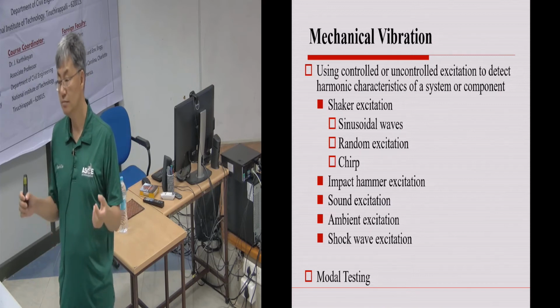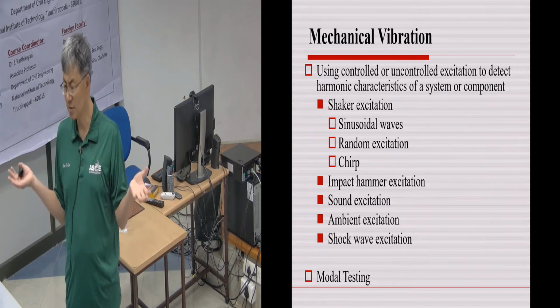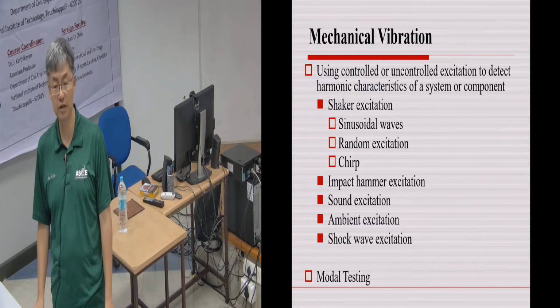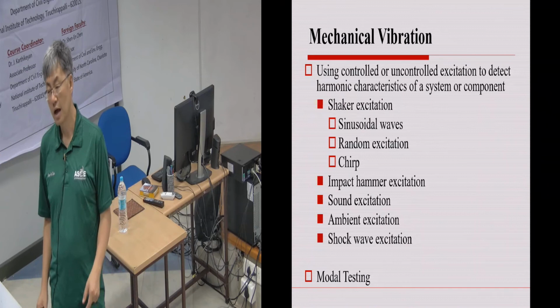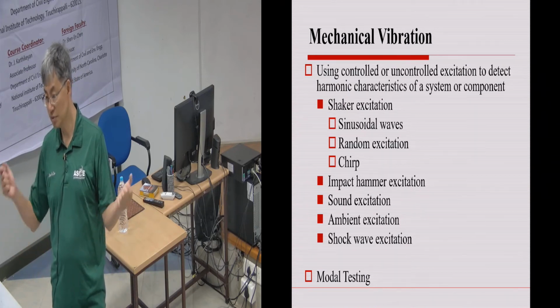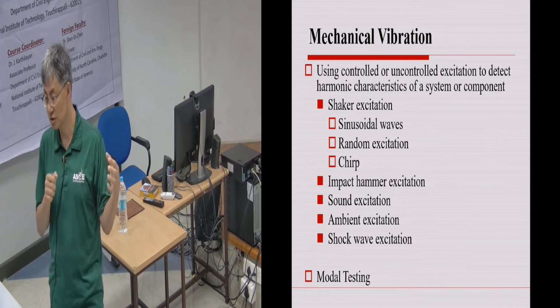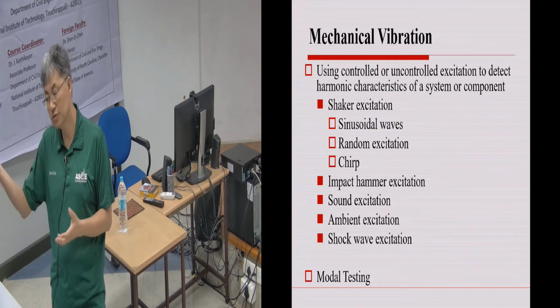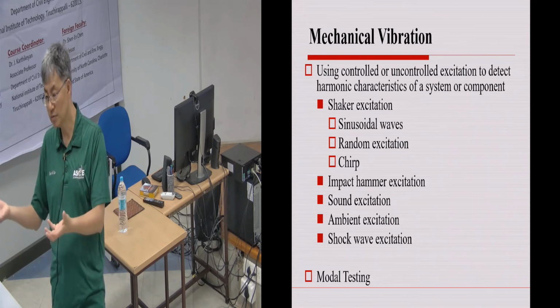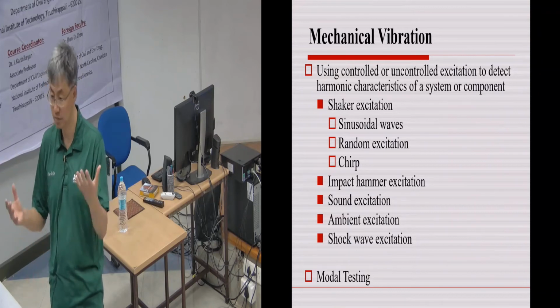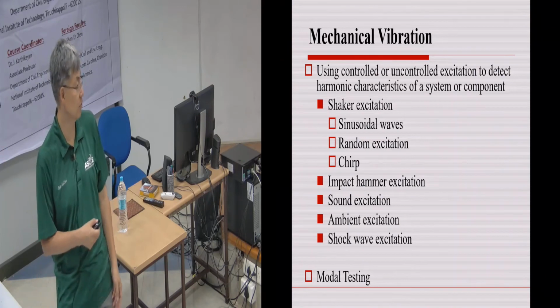Buildings naturally have some kind of movements. Even this building, as we sit here, we don't feel anything because it's so low. However, if you want to be able to detect damage, you need to shake the building, so you need to use a shaker. The shakers also come in different ranges, so you need to match, apple to apple, the right frequency sensors with the right type of shakers for the building or bridge or whatever structure you're talking about.